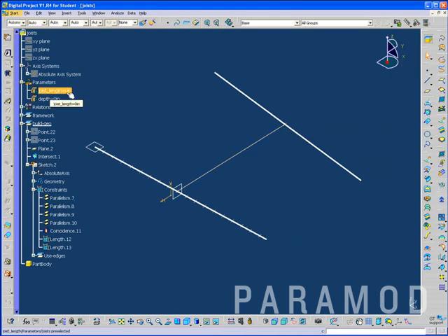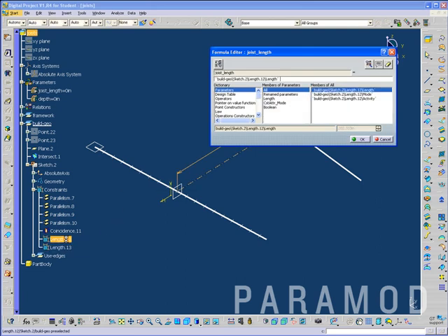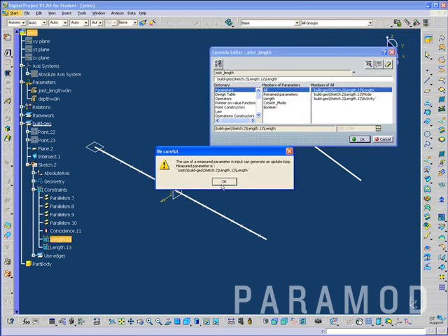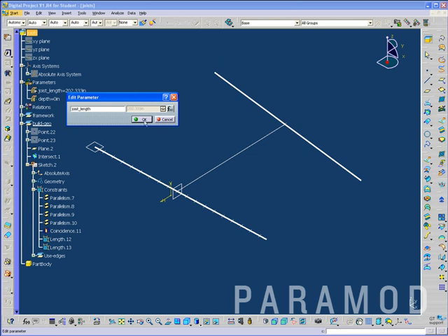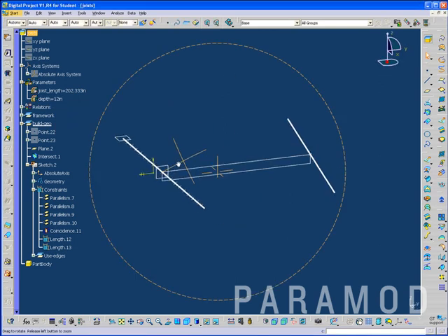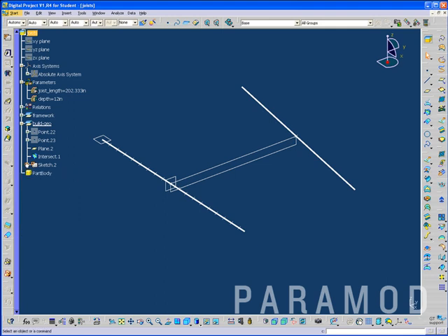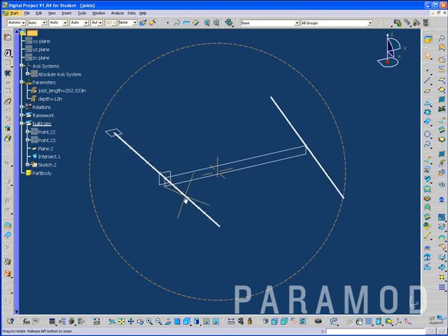We'll just exit for a second. Joist length. We'll edit this formula and set this equal to joist 12. It tells us it can create a loop, but for the way that we're using it, this will be fine. So we see that we get that value. And for depth, maybe we'll just make something 12 inches so we see where it is now. And again, I want to hide that absolute axis for the sketch. And then I can minimize the sketch as well.